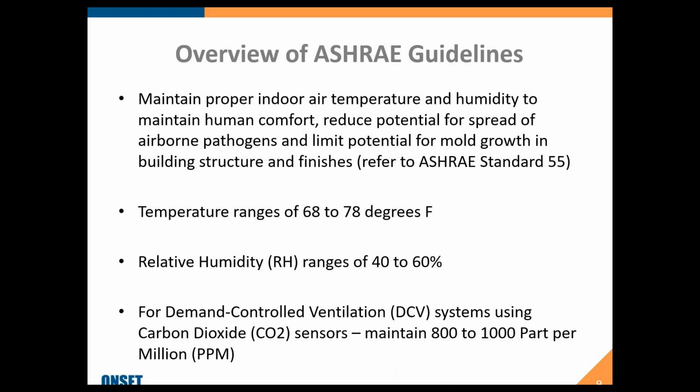In terms of temperature and humidity and looking at human comfort, there are ranges that you'll want to maintain: 68 to 78 degrees Fahrenheit, and humidity levels of 40 to 60%. It was interesting. A number of us have been listening to a lot of these webinars about what we should be doing, and some of this depends upon where you are in the country.